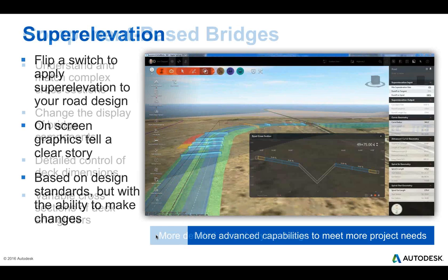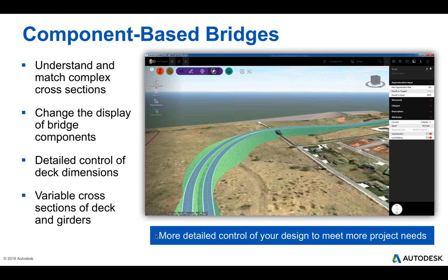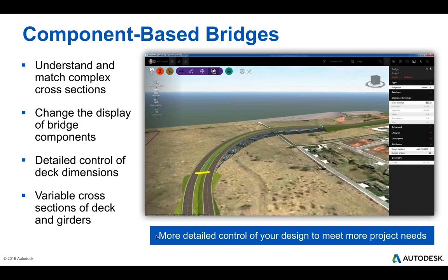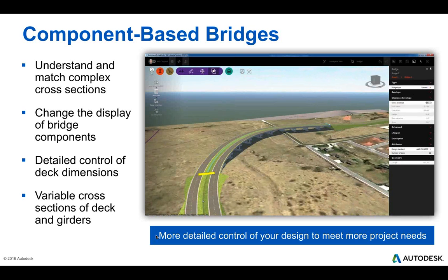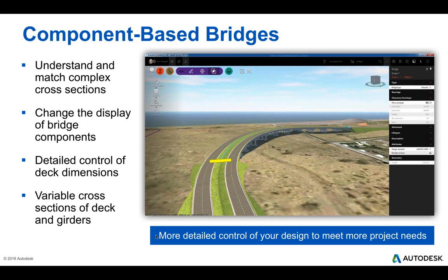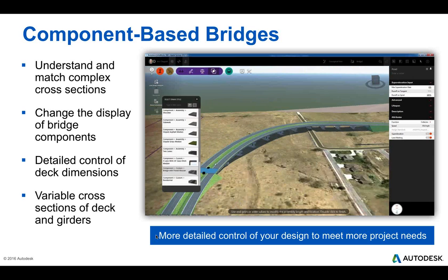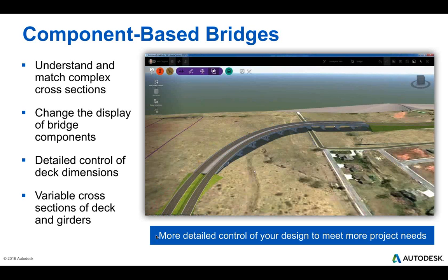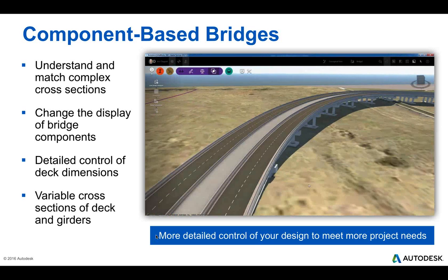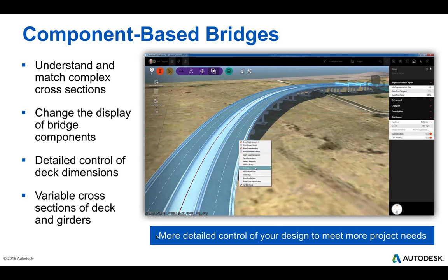The next piece is about bridges. That's work we've been doing for a long time on Infraworks, and we are improving more and more how we can design bridges. We can do all the sections and the columns on that bridge, and that's a better design instead of just putting some random or stub elevation and columns there. So you can do a very good design inside Infraworks before you go to the structural analysis or the other pieces of the project.